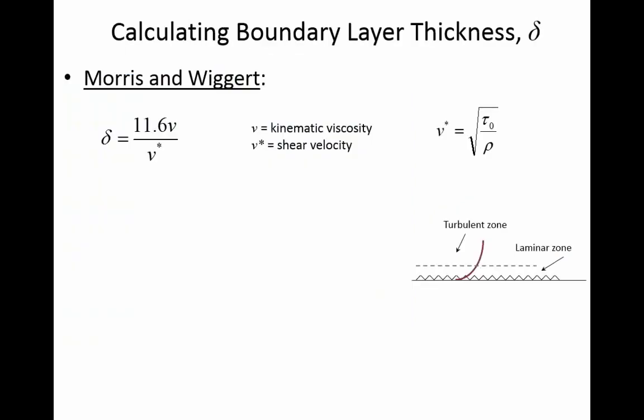Okay, back to the boundary layer. We're just talking about how different metals have different roughness heights. Here, these little ridges represent the grains, maybe in a cast iron pipe, or they could be the corrugations in a corrugated metal pipe. Whatever the material is, it has little bumps along its edge. You may have to zoom in really, really close to see the bumps, like in the case of a plastic pipe, where plastic pipes are really smooth.